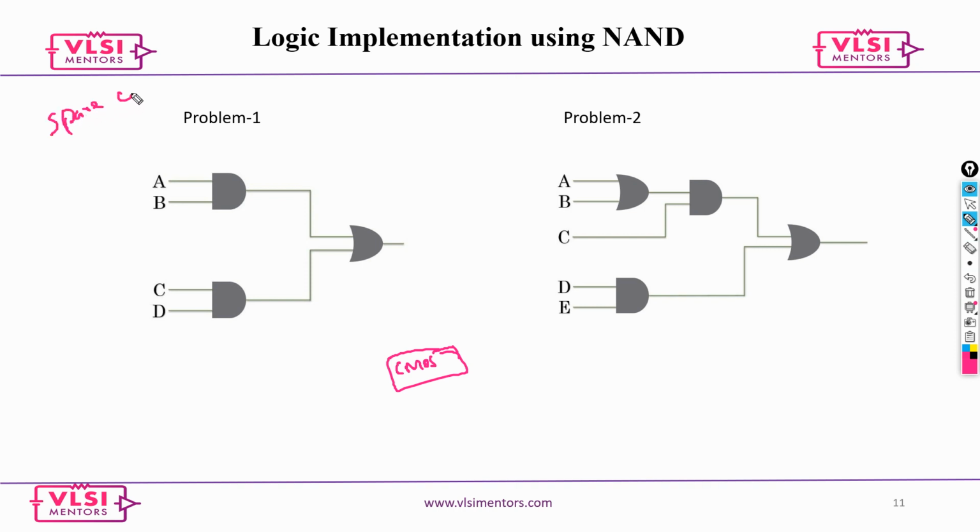PD guys will have to add spare cells, and those are always universal gates, because you don't know whether the chip will work 100% or not. If any bugs are found, you would use these spare cells to repair or fix that bug. It's like when you are going in a car, you always ensure that a stepney is there. So this is sprinkled everywhere in the design.